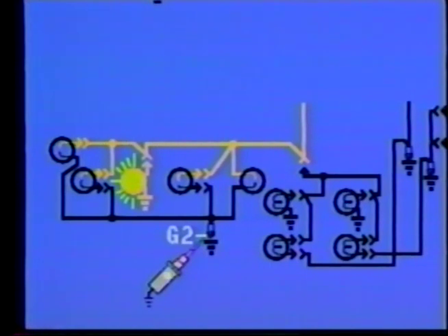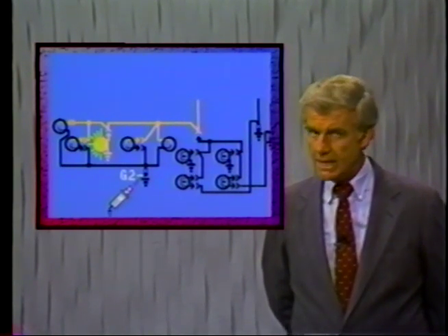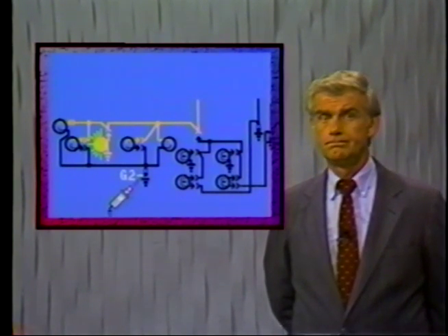Consider which answer would be correct if, in addition to the given information, you were also told that a test light connected between chassis ground and ground 2 did not light. Would your answer change? Well, yes, it would, because now we know that the connection at G2 is good. Otherwise, the test light should have lit. In this hypothetical case, then, all four bulbs simultaneously could have blown out.